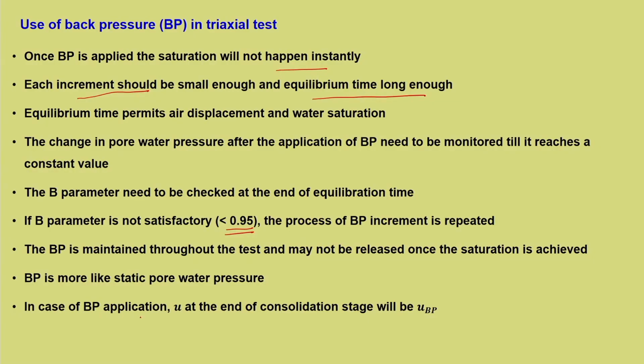Only the excess pore water pressure brings about volume change in the soil mass or densification in the soil mass. This we have seen. So, here back pressure will not bring about any such changes. So, it is more like a static pore water pressure. So, in case of back pressure application, U at the end of consolidation stage will be U of back pressure, that is there will be some amount of pressure already existing in the sample. If back pressure is not applied for saturation, then U at the end of consolidation stage will be 0.